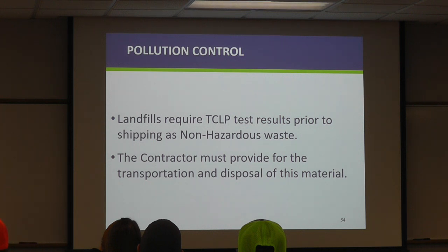Now, if you're not sure whether or not your waste is hazardous, a lot of the bridge information that exists out there will state historical record whether or not it's got a lead-based primer. If it does, you already know. You're treating the waste as hazardous, not an issue. If it's unknown, or you're just not sure, you can do a TCLP test on the waste you end up sampling. It's a toxicity characteristic leaching procedure. Basically a fancy way of saying, will the lead in the waste leach down into the soil and the groundwater?